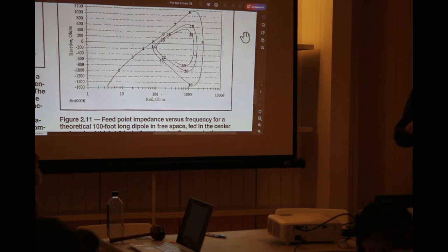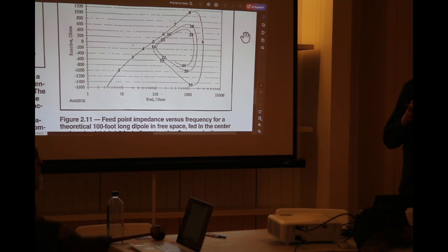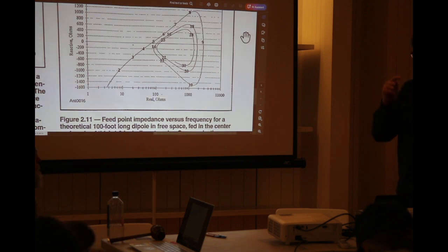I don't have time to demonstrate the two-port method, but one thing the VNA will do, and your average antenna analyzer will do, is a two-port measurement, where you want to actually measure through a filter. The calibration procedure is pretty much the same. You do the normal calibration procedure, then you take a transmission line between port 1 and port 2 and do what's called the through calibration. Then you do the isolation, where you put a separate dummy load on each of those ports, and then you calibrate that. Now you're calibrated to do all your measurements through a filter or anything else like that.